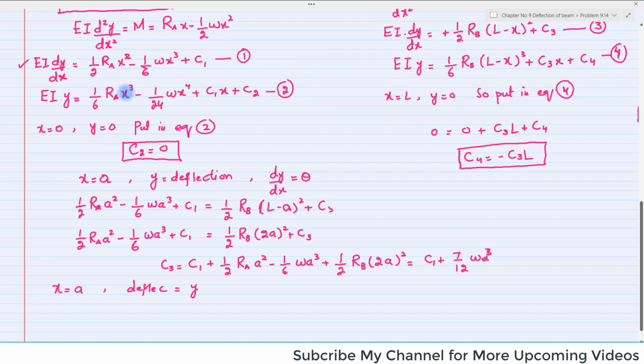So again, if you put x is equal to a in equation number 2, that will be equal to 1 over 6 RA a cube minus 1 over 24 W a to the fourth plus C1 into a plus C2, which is again 0, so there is no need to write C2.